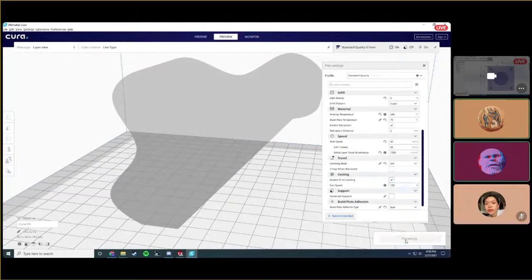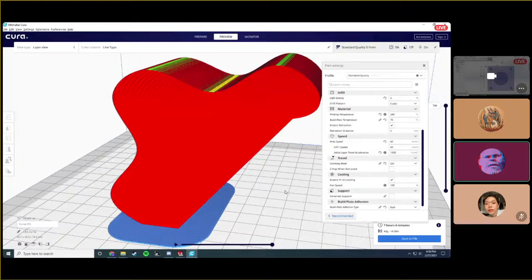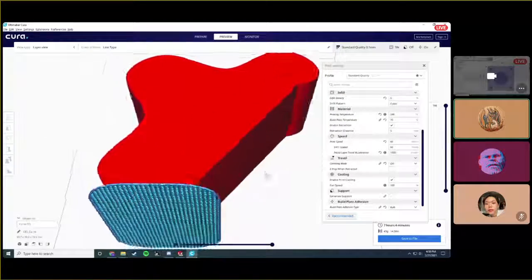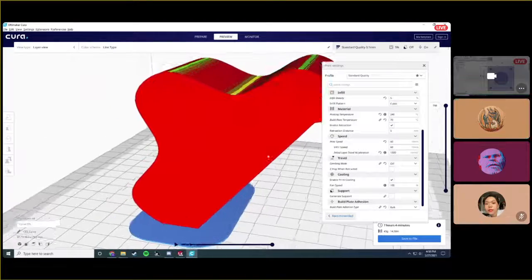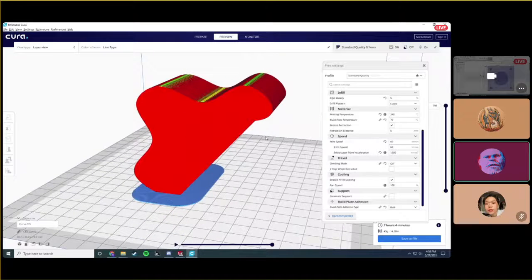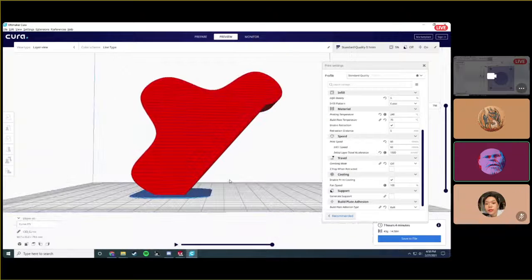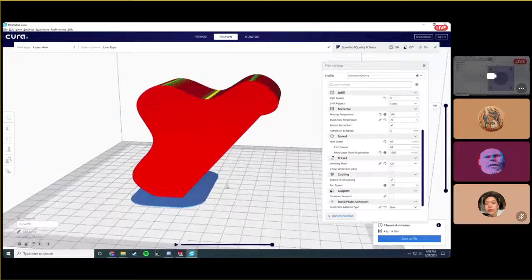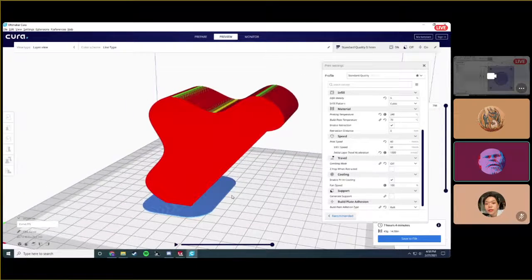But yeah, your print would definitely fail. If you ever see something like that, you should always verify your print in the preview tab. It was just a weird glitch. Now it's fine. So you should definitely look for stuff like that, because your whole print would fail, and reprinting that same G-code would just fail again. Wow, that was odd.